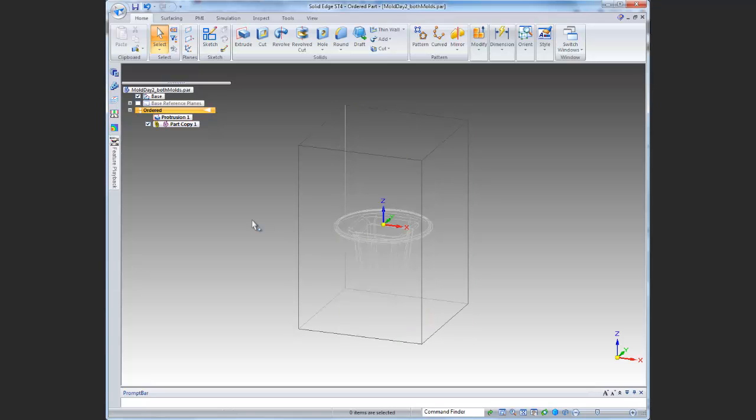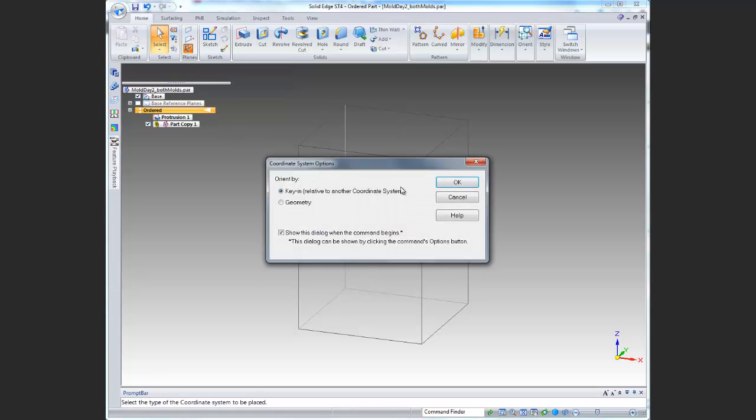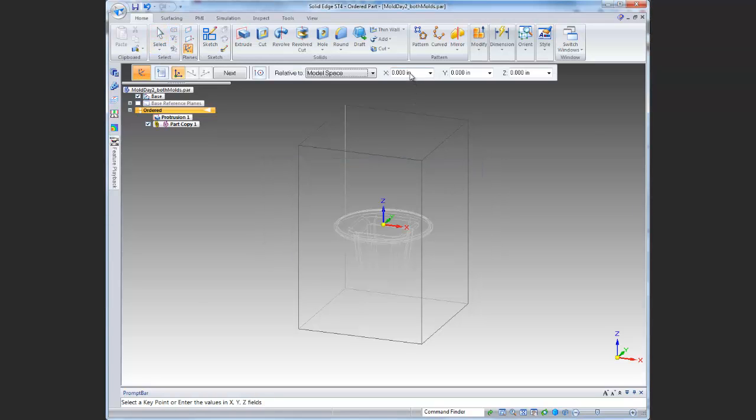If you do want to move it to a different coordinate system, you can create those by creating a new coordinate system. And then when you bring it in, you can just put it on that coordinate system. So if you have something that's not centered, you can move it to a different coordinate system. I'll let you figure that out. It's actually fairly easy. You typically just key in a coordinate system. Like let's say I wanted it moved over 2 by 2. It would make a new coordinate system out there for me. I don't want that for this, but I thought I'd show you that because some people do use it to put it in a different spot in their mold technique. Alright, so let's go ahead and do some more steps.